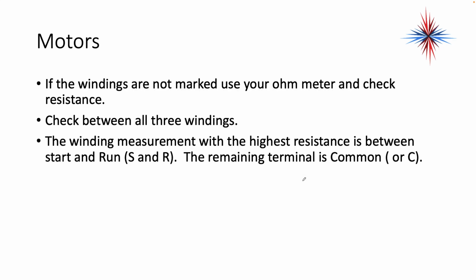If the windings are not marked, use your ohm meter to check the resistance. Check the resistance between all 3 windings. The 2 pins with the highest resistance are going to be start and run. So if I have 3 pins on the outside.